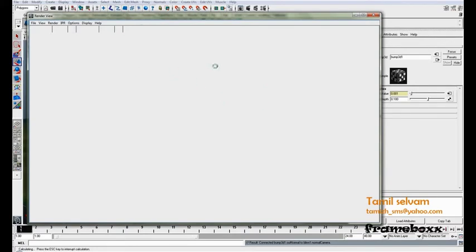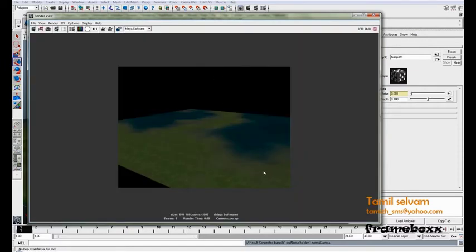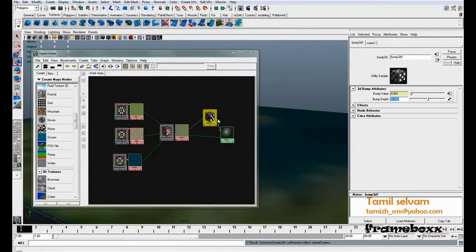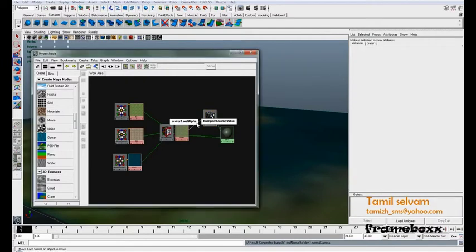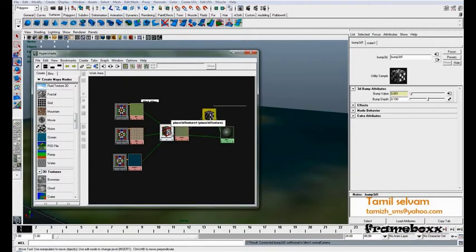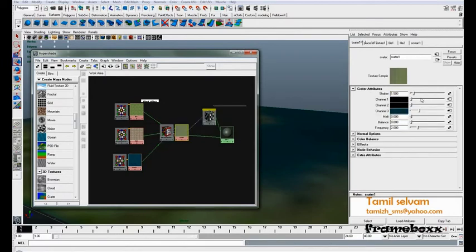Just render and see how it looks. Okay, fine. You can see the bump over here, but here you will not see any bump. That is because this is taking an alpha value. It means luminance out alpha, but these textures are connected with color right over there, so this will ignore the bump for these textures because it's color information. This is taking alpha information.